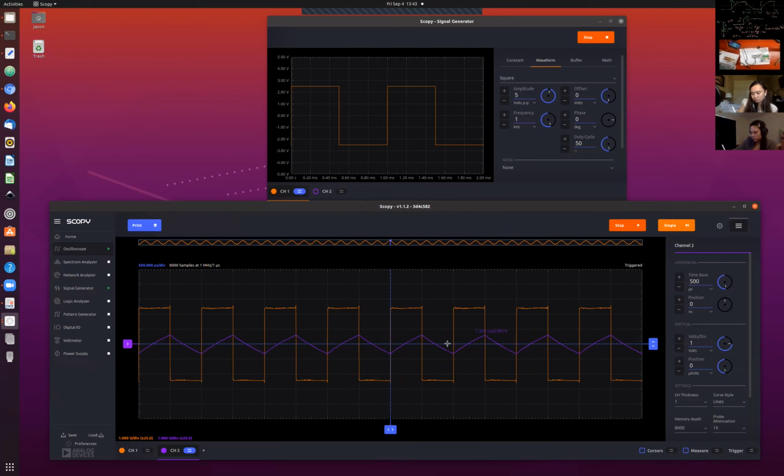Now this is going to be our next circuit that we talk about. It looks exactly the same, but it's going to be an approximate integrator. So if you think about the integral of a constant positive number, well, the integral of a constant positive number is something with a constant positive slope. And the integral of a constant negative number is something with a constant negative slope. And then a constant positive slope, constant negative slope, constant positive slope. So for the case where we don't allow the output to change very much, this circuit acts like it's a pretty good approximation to an integrator.